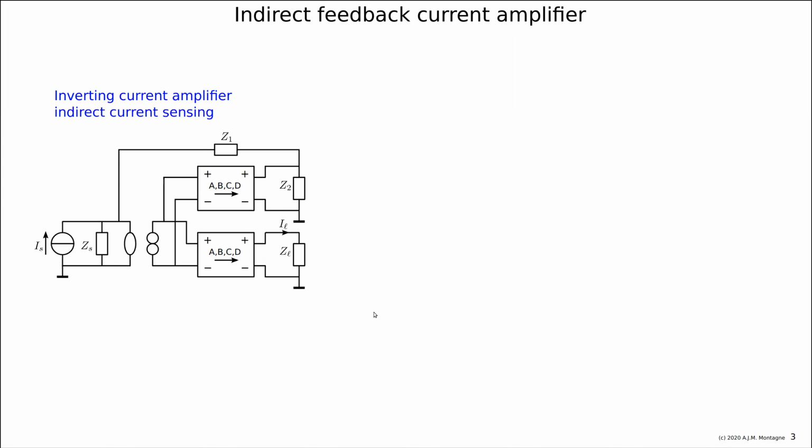Now look what we are going to do. I'm going to replace both blocks ABCD with one transistor, and then I say, well, let's keep the upper transistor. You see, it is in the loop. The upper ABCD block is in the feedback loop together with the nullor. The lower one is not in the feedback loop. It's in the transfer to the output, but not in the feedback. So I could also say skip the nullor or use the other transistor as the one and only controller, and